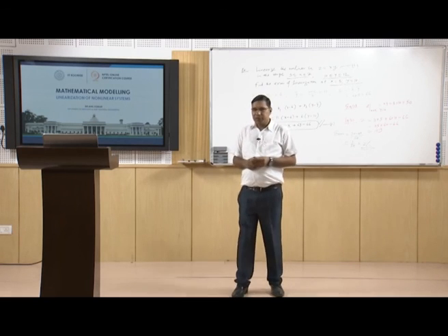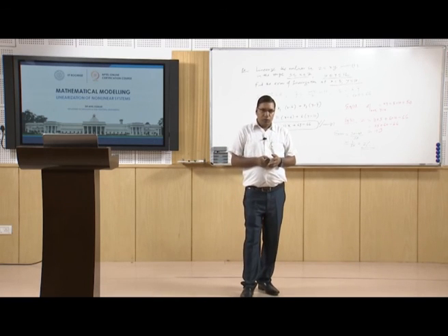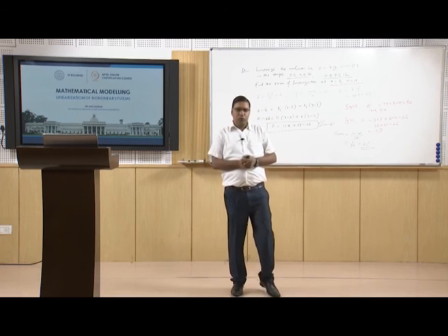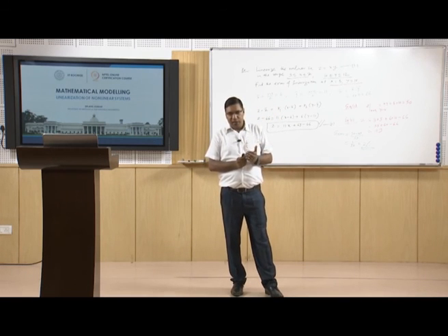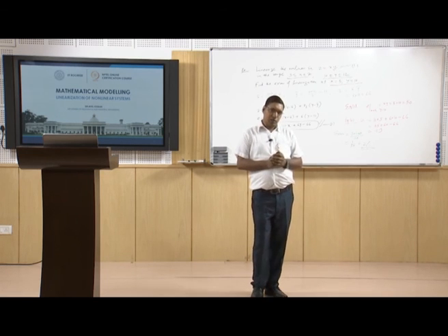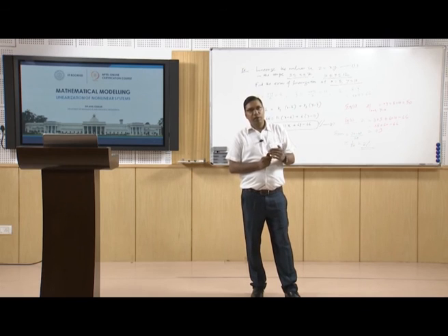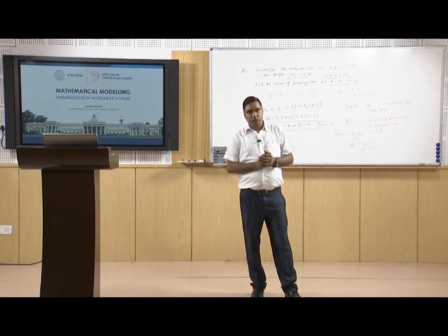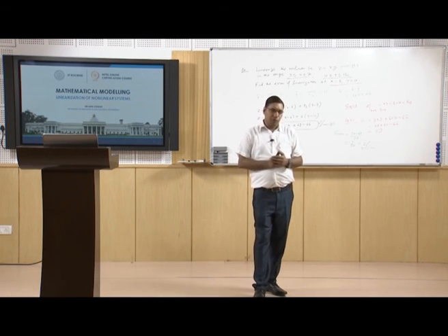So here we learned how to linearize a nonlinear system when the operating range is close to some equilibrium point. We can linearize that nonlinear function about that range, and once we are able to linearize, we can write the transfer function for that nonlinear system in that range, and that will help us to study the system using the transfer function.